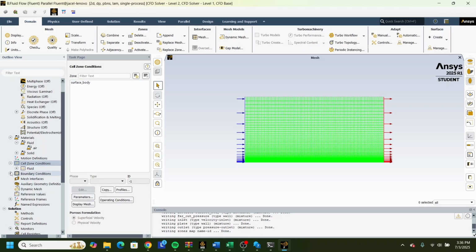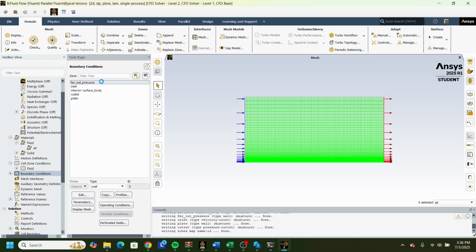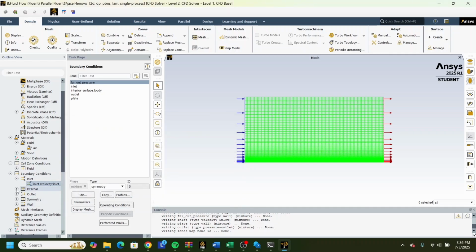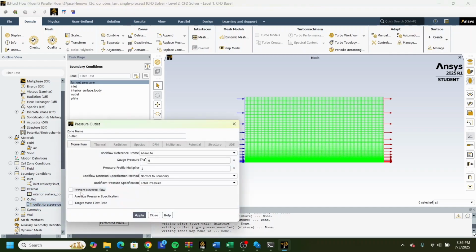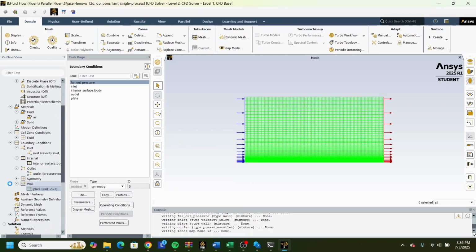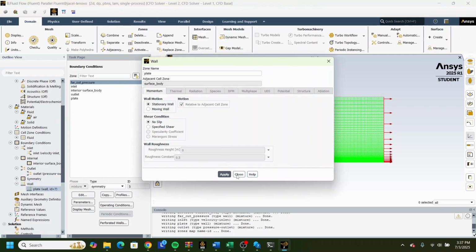So yep. Boundary condition, and then double click on boundary condition, go to forward pressure, change it to symmetry, click apply, and then click close. And then you want to go into here, change your inlet. So the assignment says this should be at 2 meters per second. Click apply, click close. Enter an outlet. The outlet, you should prevent the reverse flow. Apply and close, and you shouldn't need to change the wall. Right, you have no slip stationary, and okay, it's all good.